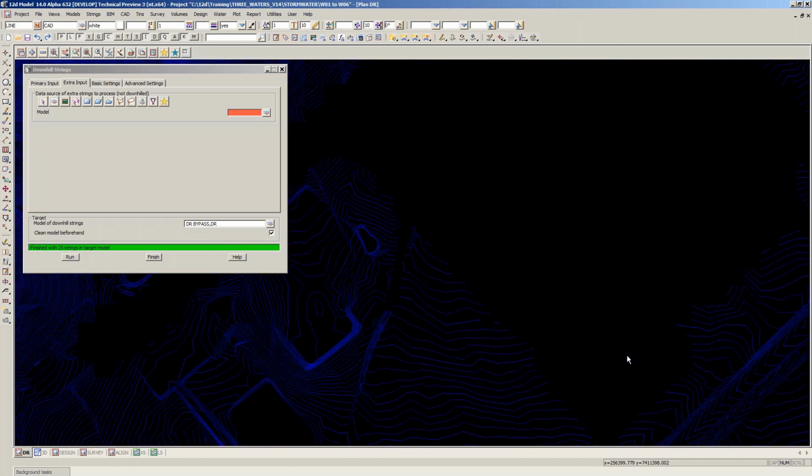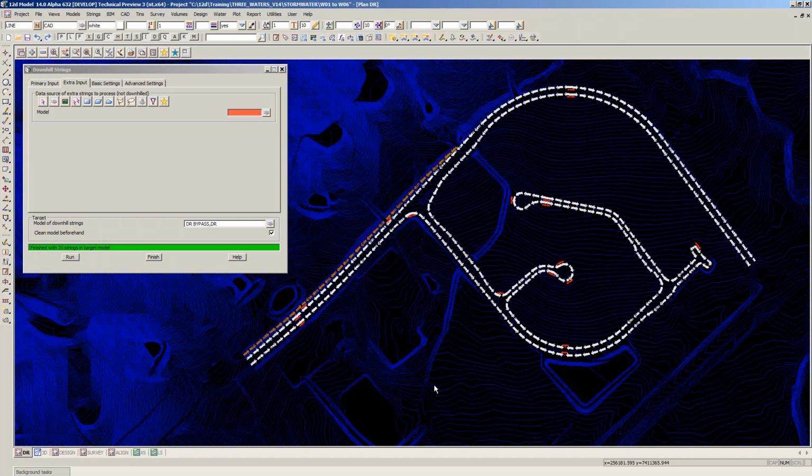And this is the art of 1D modeling, I guess. It's drawing arrows on the screen and imposing our will on the water. You generally don't have to mess with any of this sort of stuff if you do 2D modeling, because you just provide a surface and add water, and the governing equations are solved, and it works out where the water flows.